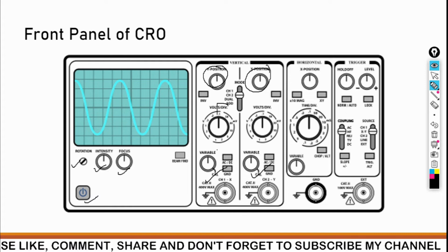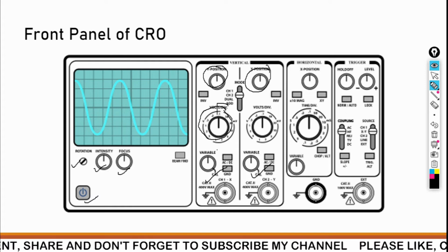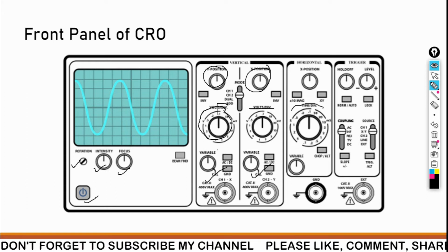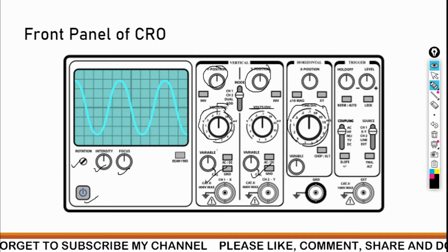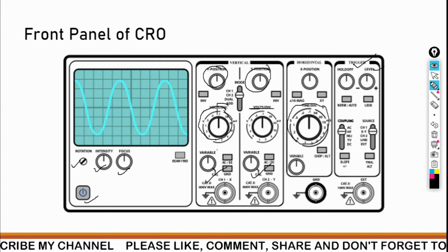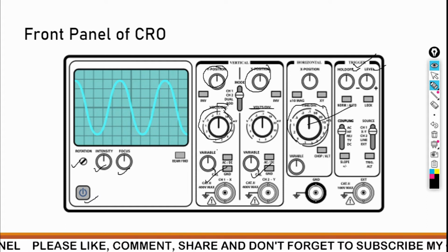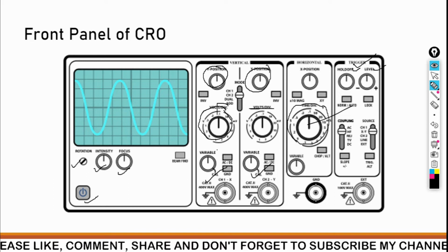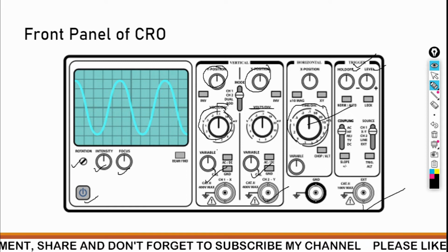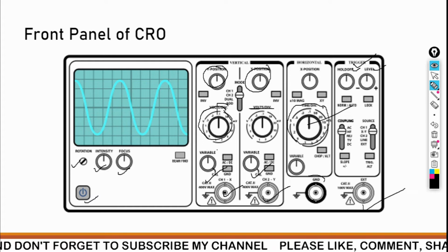This is a voltage per division knob. This will adjust the voltage per division of these signals. This is also voltage per division. We can say vertical deflections, and this is for the x direction deflection, or we can say horizontal deflection. This is the trigger pin where we can have a level hold off that will get adjusted. So this signal will be adjusted and then we can do the measurement. This is again for the external world, and this is for channel Y, and this is for channel X. This is the pin that is used for the ground.